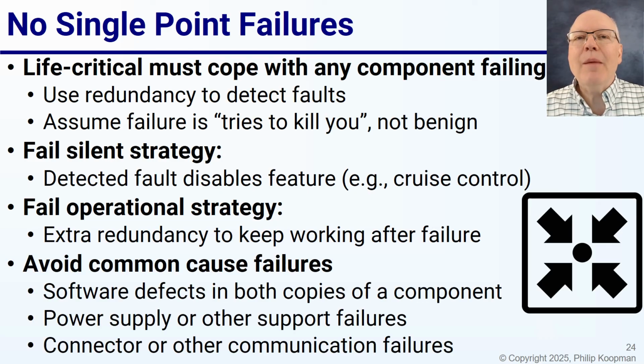You need to avoid common cause failures. It's not just a single component fails and causes a problem. You can have multiple failures that are correlated. So you could have two copies of a hardware component that both have the same software and that software has the same defect, and that's going to be a problem. That's a common cause failure. You could have one power supply that feeds two different chips. Well, you have two chips, but if you lose power, they both go. Or you could have a connector or other communications failure. So there's two independent signals on the same connector, and the connector comes loose, you've just lost both signals.